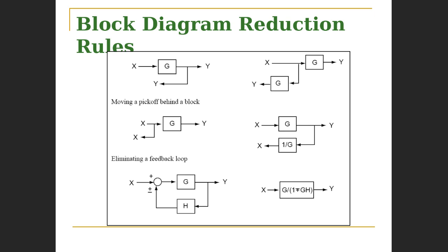All right. So y is actually the signal that is here. I was simply extending it to provide it at another point. Right. So I could even do this once more. We're just simply extending the signal Y to some other point. Okay, so whatever is here will appear at all points along that pickoff point. Okay, so now what we're interested in doing is to move this pickoff point from the output of G to the input. Okay, so what we're picking off here was Y.